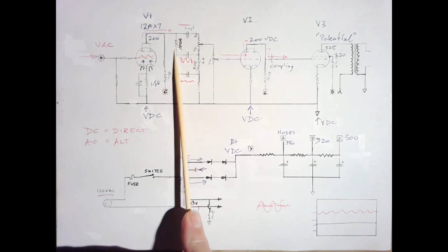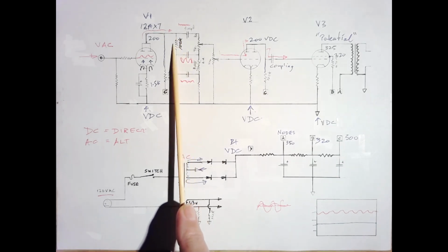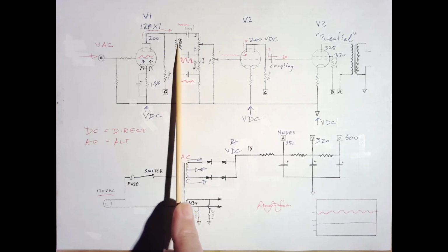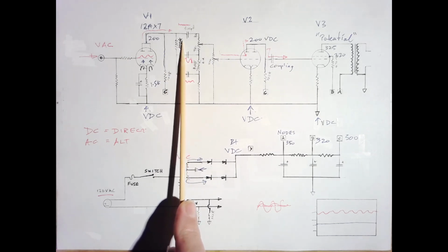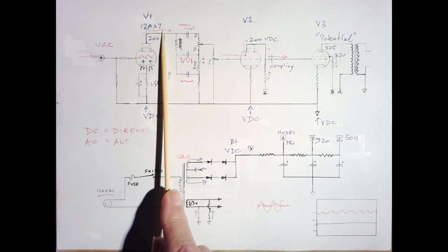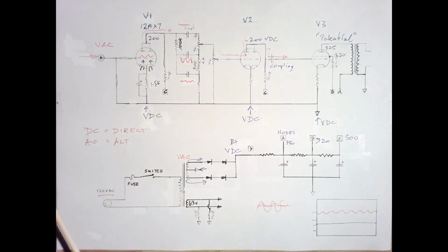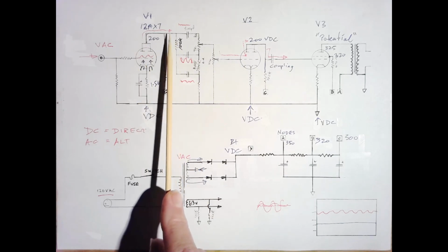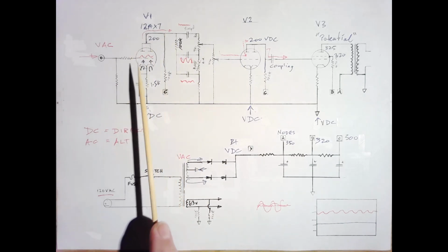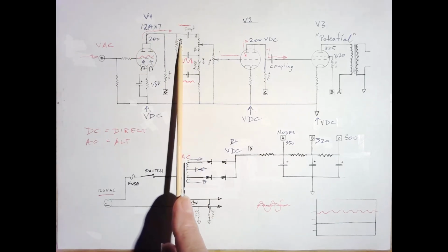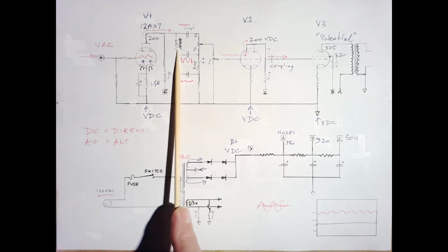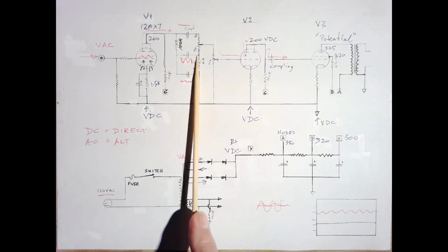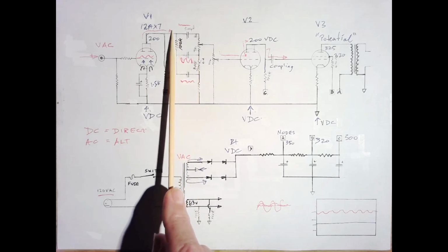So we have what is called a slope resistor here. I was working with somebody who accidentally put a 100 ohm resistor in here instead of a 100K resistor, and the amp, when we fired it up, had no treble control. The treble pot did not work. And that is because the signal goes to the path of least resistance. A 100 ohm resistor here is nothing. It came zooming down here, right through here, and right through here. It was very happy to do so. But when you put 100K in here,